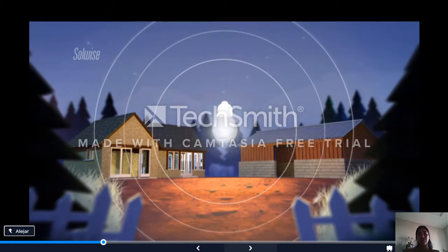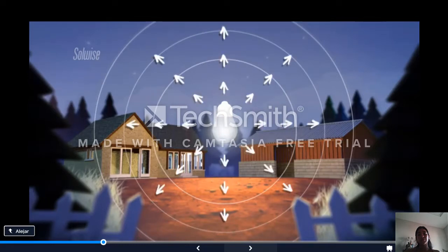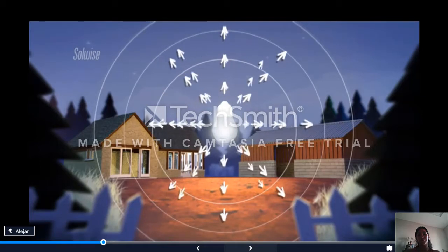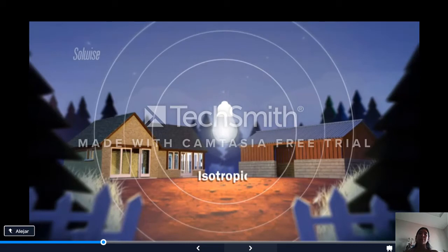Now, let's assume that our light bulb takes 1 watt of electrical power and radiates 1 watt of light. We would say that this antenna has no gain, or to put a number on it, it has a gain of 0 decibels, or 0 dB for short. It's a simple bulb and it radiates equally in all directions, up, down, left, right, forwards and backwards. The technical word for this is isotropic. Our light bulb has an isotropic radiation pattern.